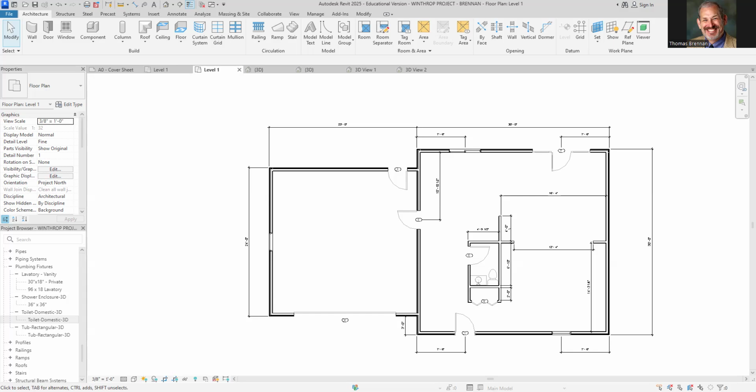And then what you do is you put in your wall opening. So you click on the wall you want, and then I'm going to make the rectangular opening here to here. 12 foot. I'm going to make it 12'4". And then this is going to be 2 feet, because that's what the side has to be to center it. That kind of resolves that issue. Does that help a bit? Yep, that's pretty much all I have, other than tags.